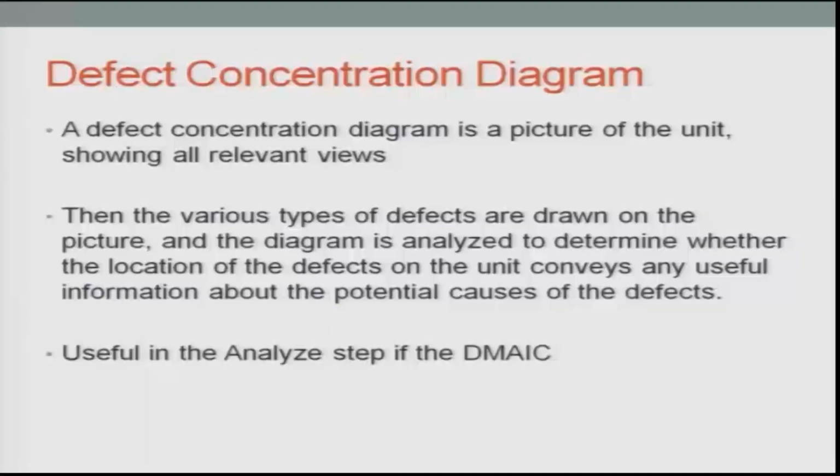Defect concentration diagrams are there. A defect concentration diagram is a picture of the unit showing all relevant views. Then the various types of defects are drawn on the picture and the diagram is analyzed to determine whether the location of the defects on the unit conveys any useful information about the potential causes of failure, or causes of not so efficient performance of the system.